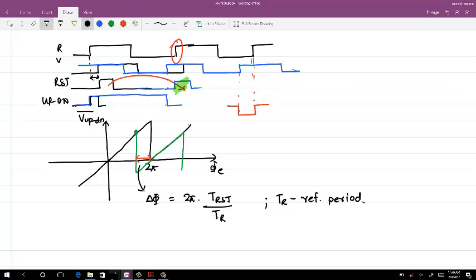If you remember the XOR or SR flip-flop based phase detector, the average on the positive phase side was 0. You have a positive and negative, whichever one you looked at, right? Now, with this kind of phase detector, I'll end up in the same region, meaning I'll end up having an average 0 for the positive phase error. What should be T reset?